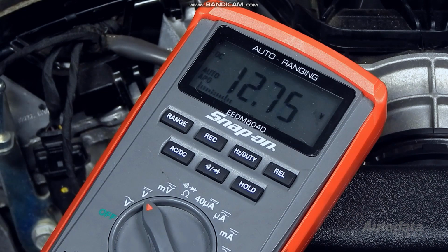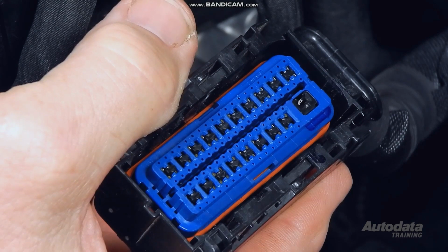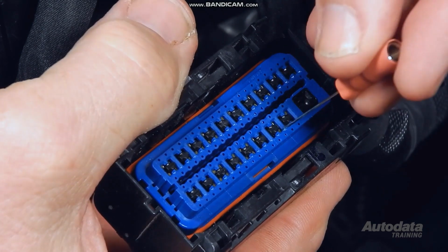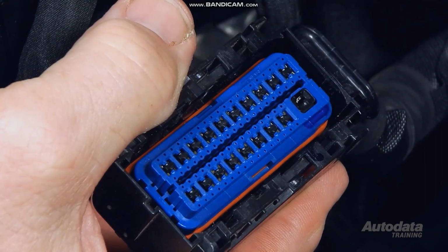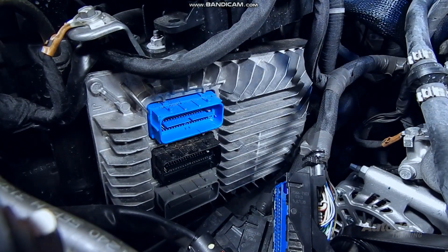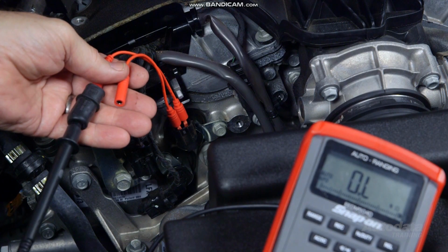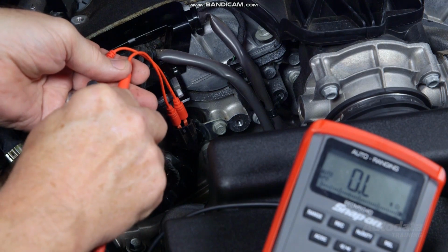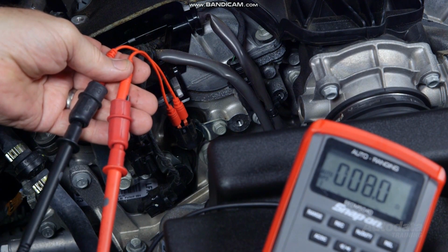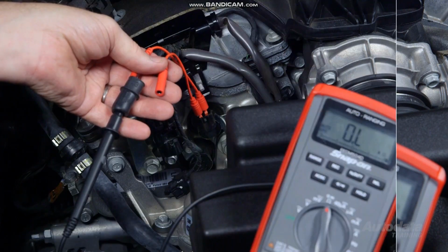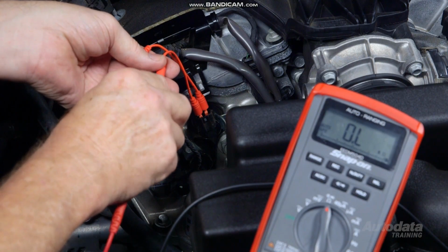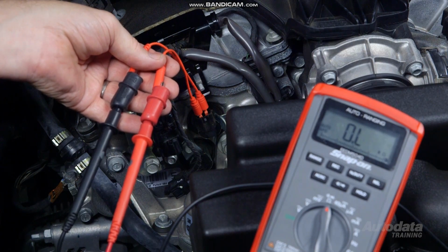If there is a voltage here, then check the control circuit for an open circuit. Should you still find no voltage, then test the connector for terminal tension and corrosion. The module will be at fault if no problem is found with the terminal. Should both circuit tests reveal no faults, you can then check the actuator. Using a multimeter set to ohms, check the resistance of the actuator and compare it to specifications. An incorrect reading or an open circuit indicates a faulty actuator.